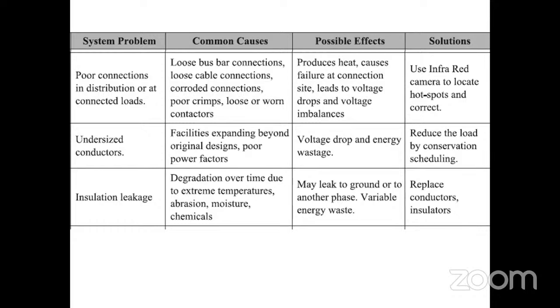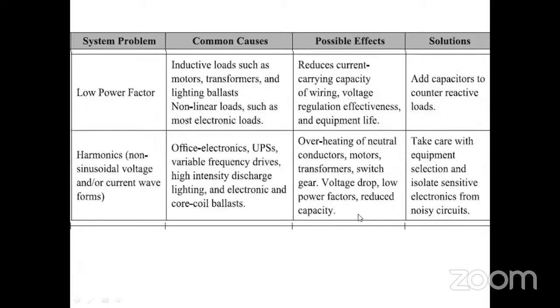Insulation leakage will also waste energy, as current may leak to ground or another phase, which is energy waste. Replace the conductors and insulators. That's all. Low power factor will reduce the current carrying capacity of the wiring and affect voltage regulation, and adding capacitors will reduce the problem.